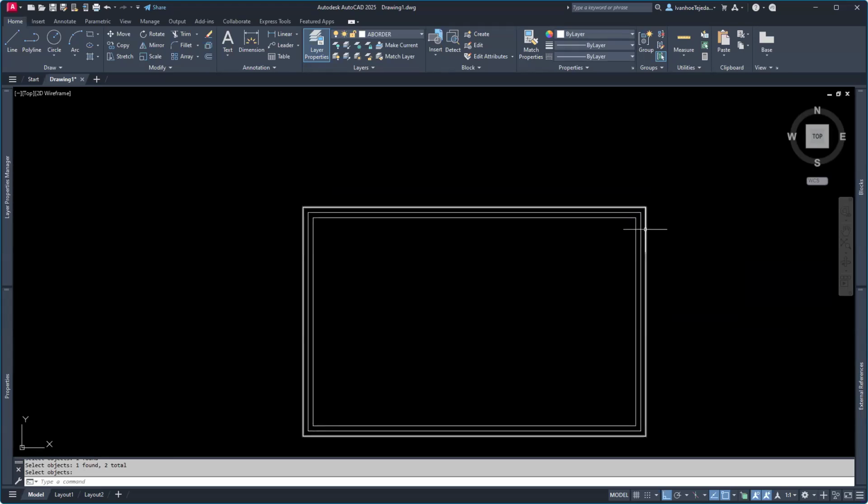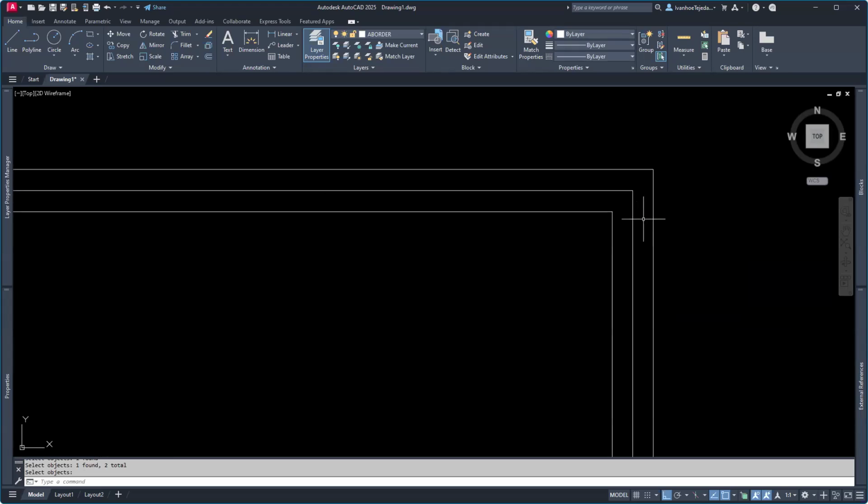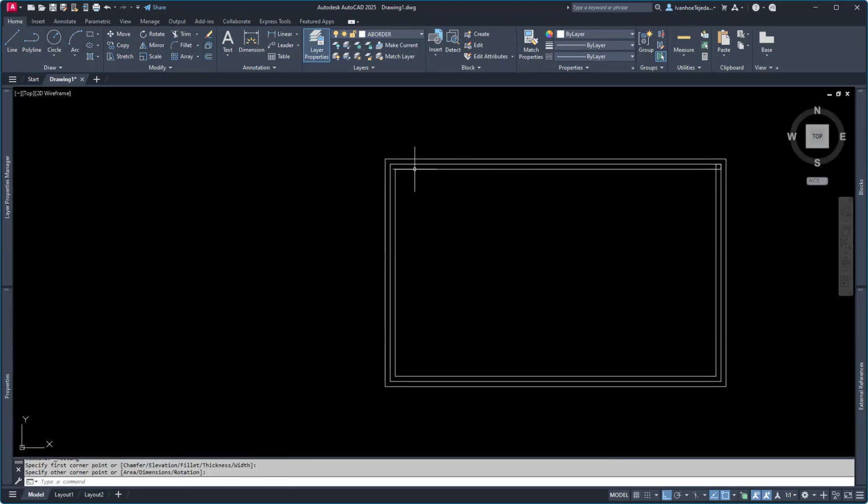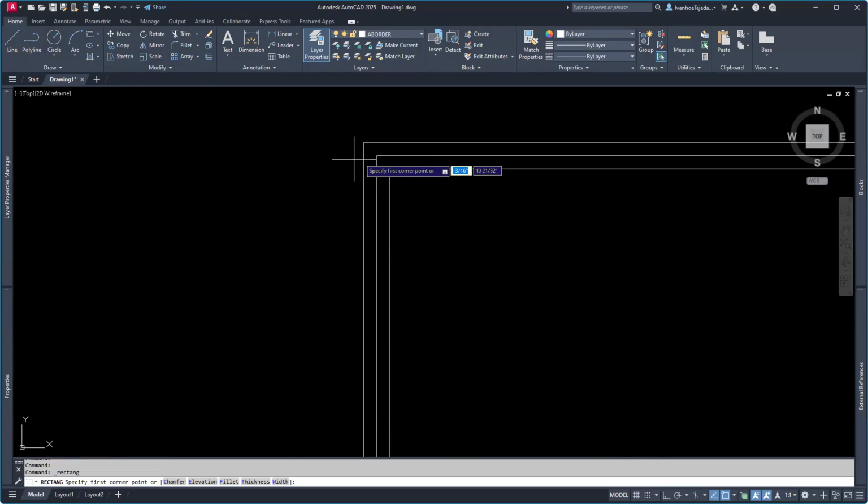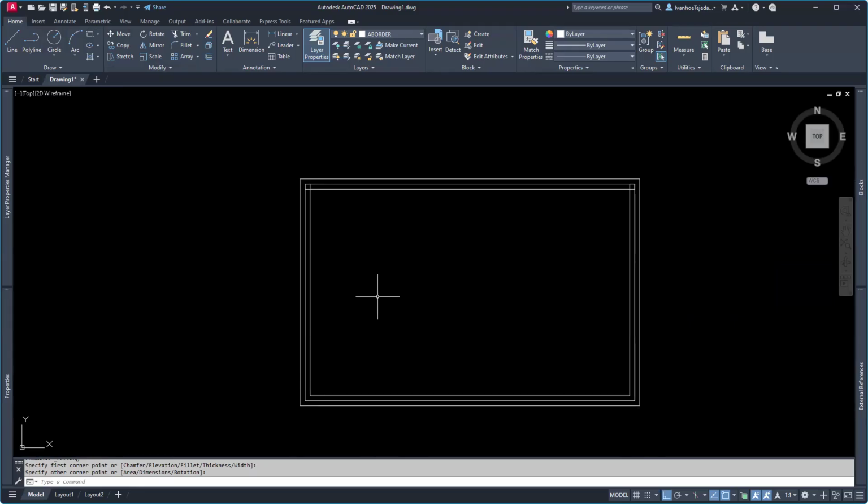And then what I'm going to do is come in over here. I'm going to draw a rectangle from this point to that point. And then I'll do the same thing on this side. And I could do it at the bottom, but at this point, I'm going to mirror this. MI, enter. Okay. And then the outer lines, don't need them anymore. They just serve their purpose. Like this. And look at the border that I now have.